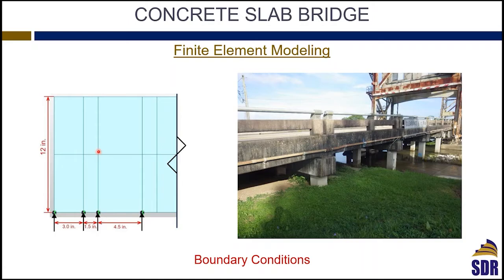When you put a hinge and a hinge, you will end up having two horizontal reactions that will contribute to your moment. Just look at the strength of a beam that is simply supported on hinge and roller, and go in your finite element model and just change it from hinge roller to hinge and see what will happen to your beam. So the boundary conditions, I always say, it's like a lethal weapon. If you don't know how to use it, you can get results that make you happy, very small moments and shears, and you have a beautiful structure.